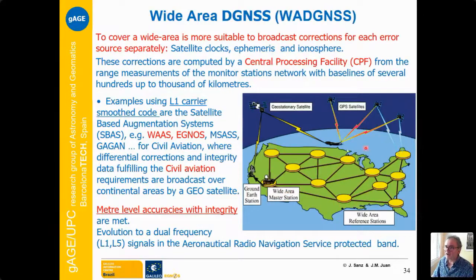The data in the reference stations are sent to the master station, which analyzes the satellite health and, in case of any anomaly, sends alarms to the user. It also computes differential corrections and confidence bounds, to allow the user to improve accuracy and, most important for safety-of-life systems, to compute protection levels.